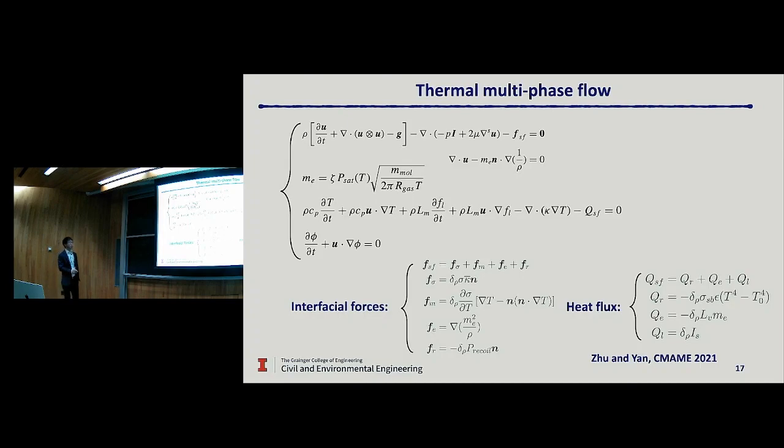However, because evaporation may happen during the printing process, purely in the gas phase or purely in the liquid phase, the flow is incompressible. However, across the gas-metal interface, because of the evaporation, the flow can be slightly compressible. So we have a model to account for this. And then the temperature field is governed by the energy conservation. Here, the energy conservation is written in terms of the temperature unknown. And then the last equation is the level-set convection, because I still have an interface capturing approach here.